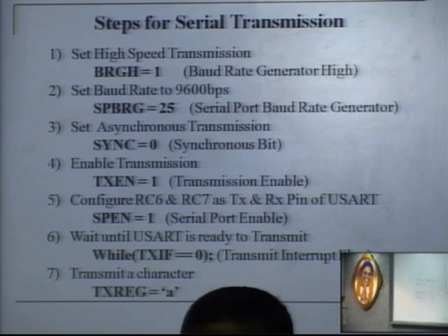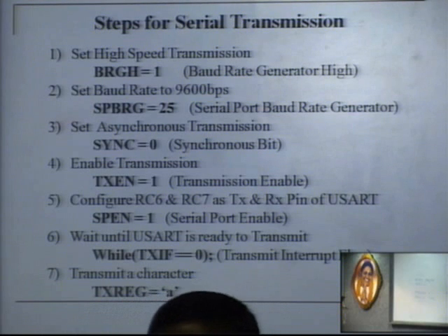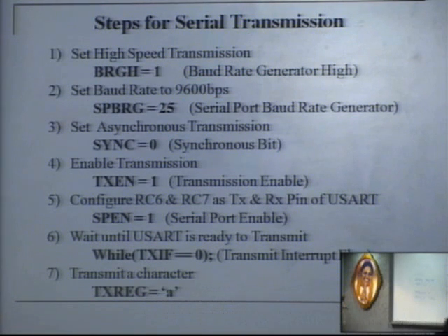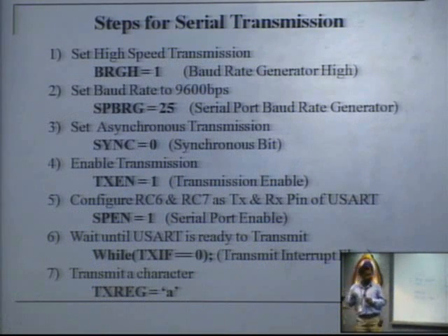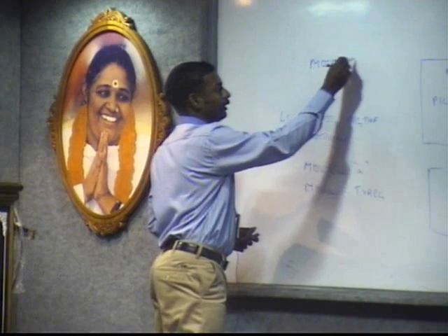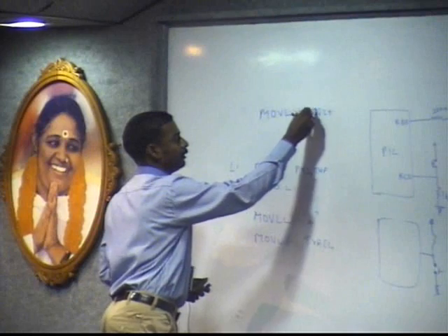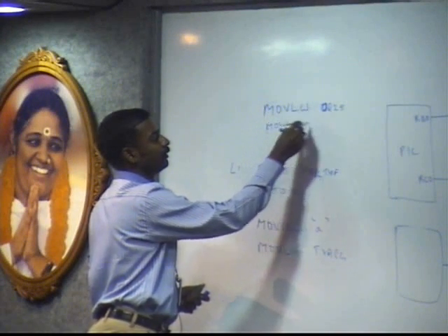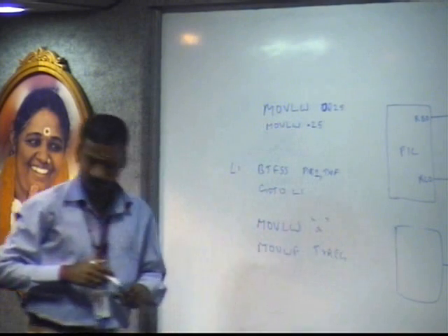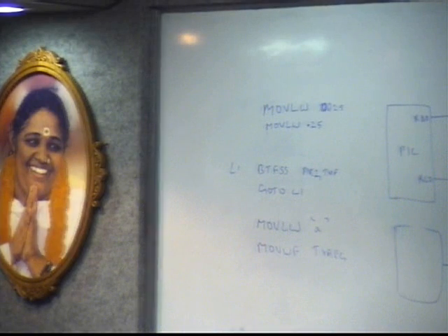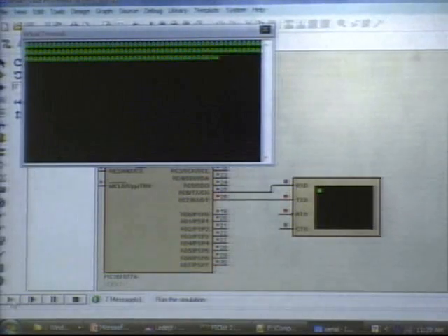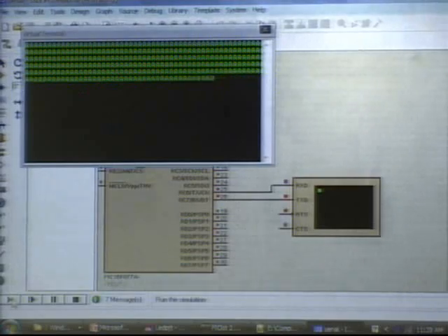So follow this step as it is. Go to loop at last. Rest all the steps are the same. And how will we move this decimal 25 using your MOVLW? Either you can write it like this, 0D'25', or like this, .25. So you can see it like this.